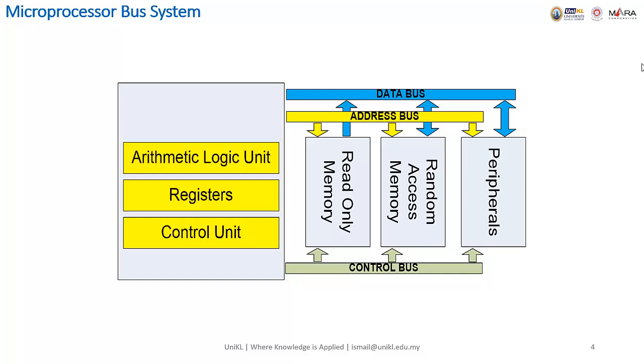If it read from a peripheral and random access memory at the same time, the data would collide on the data bus, and we would get the wrong data. So for this type of processor, we allow only one unique address to be read or written at any instant of time, not all.